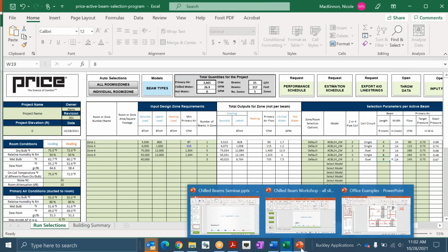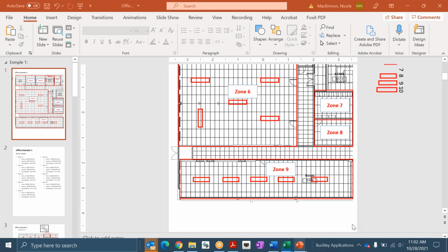So let's take that selection and go back, assuming maybe that was the server room. It's a very, very dense space. 3 8-foot chilled beams. So here's my 8-foots that I had created earlier. Let's see if we can drag 3 of these in here. And sure, I've got enough space, but I'm seeing a problem where these beams are very close together.